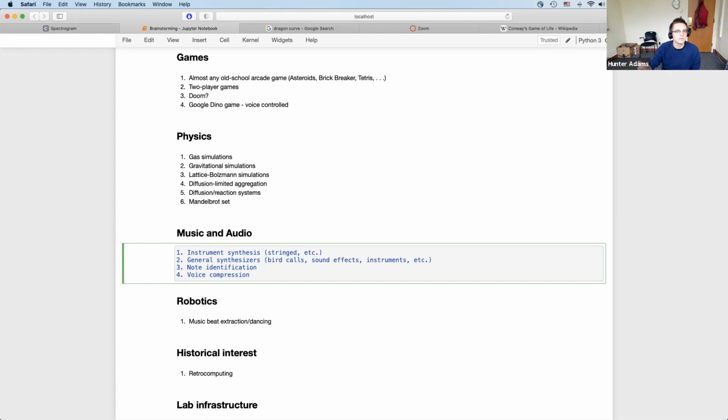Then use direct digital synthesis to additively combine sine waves with amplitudes directly correlated with the amount of power in each of those bins, and you can create very robotic sing-songy versions of your voice. Kind of cool. Voice compression and auto tuning, I will say.